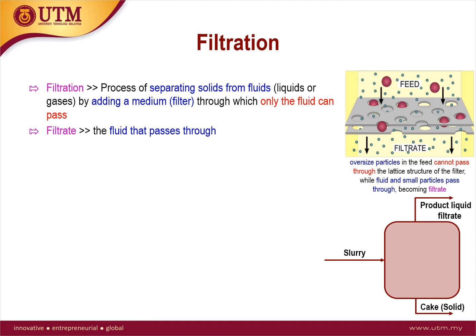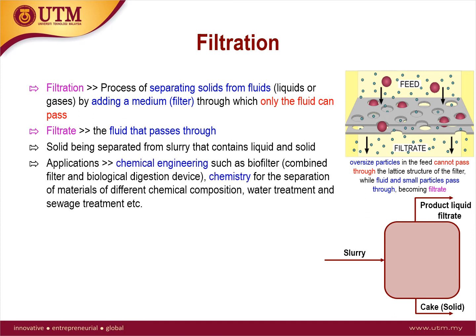The size of the largest particle that can successfully pass through the filter is called the effective pore size of the filter. The separation of solid and fluid is imperfect. Solids will be contaminated with some fluid, and the filtrate will contain fine particles, depending on the pore size, filter thickness, and the biological activity. As an application, there are various types of filtration applications in chemical engineering, such as the biofilter, which is the combination of the filter and the biological digestion device.